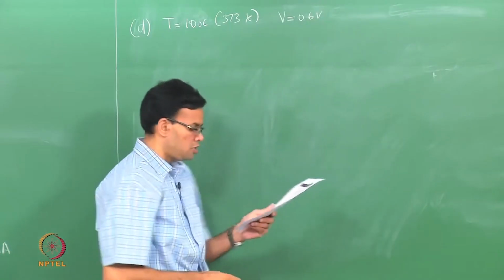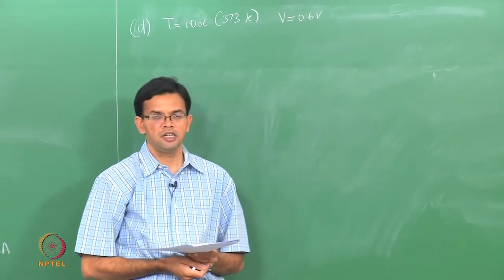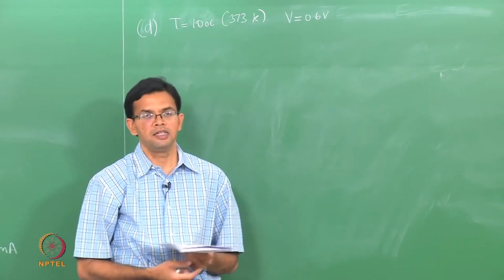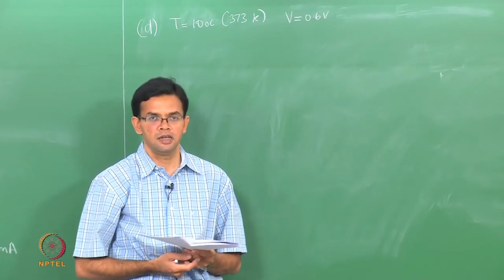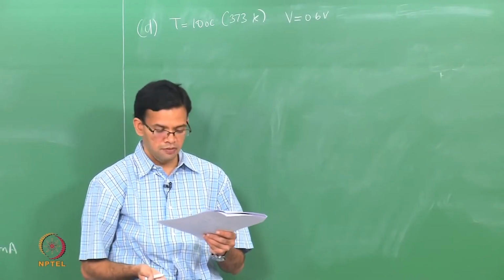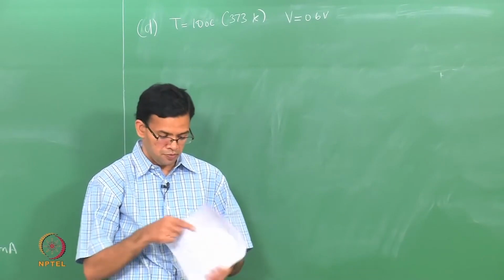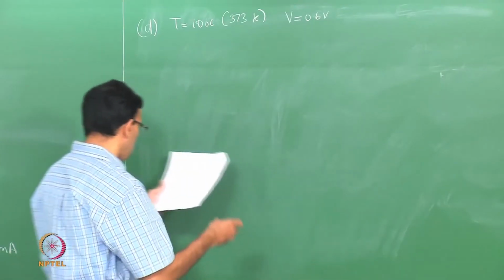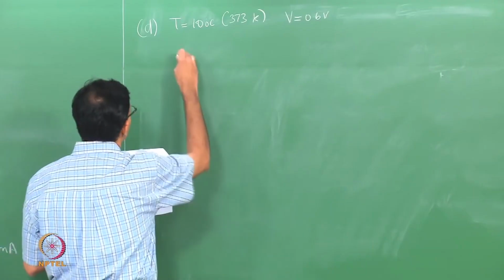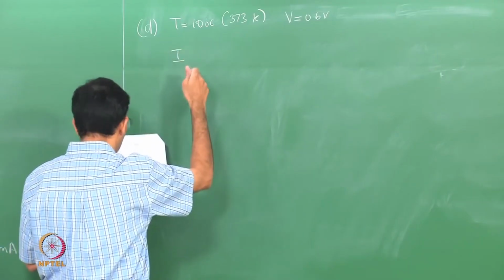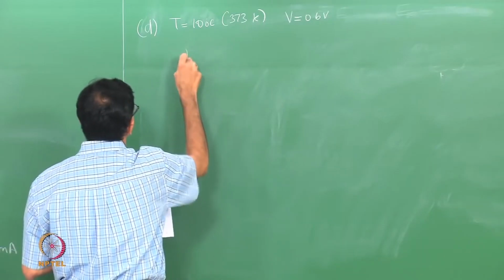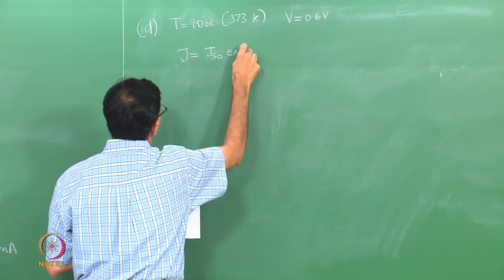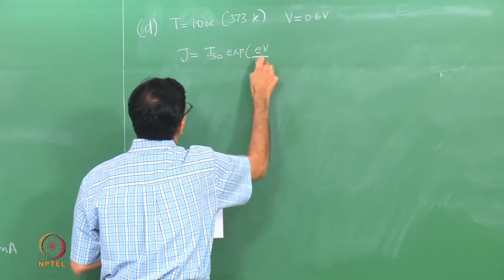The question also says to assume the temperature dependence of Ni dominates over everything else, over the diffusion lengths, the diffusion coefficients itself, also the mobilities. So, if you only take Ni into consideration, we can see that the current, or if you write this down, J is Js naught exponential eV over kT.